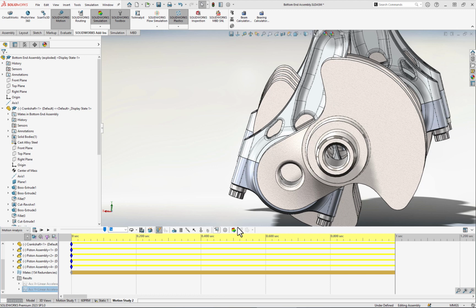these plotted results. And as we saw in those menus, there are a multitude of values that you have access to be able to plot. I would encourage you to play around with this tool and see what other things you can plot. You can plot things like contact forces, momentum values, velocities, angular velocities, position of center of mass of the part. There's lots of values in there that can be useful, and the only real way to get an appreciation of that is to experiment a little bit with them.